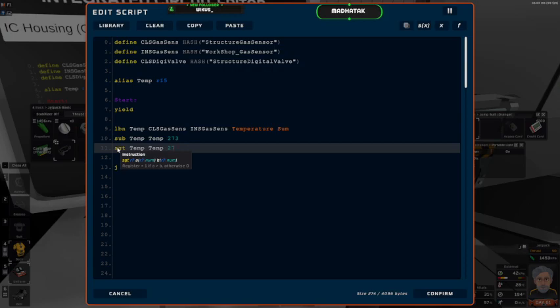So, without getting too complicated, what we can do is change this to branch greater than. So C becomes our line. Branch to line C if A, just temp, is greater than 27. And this is going to be where it jumps down to.